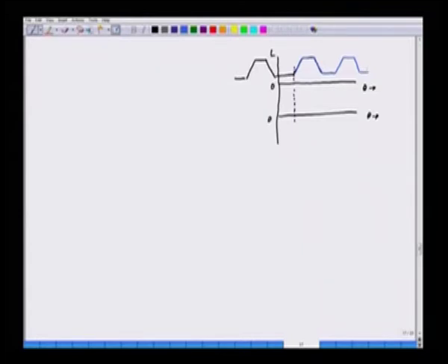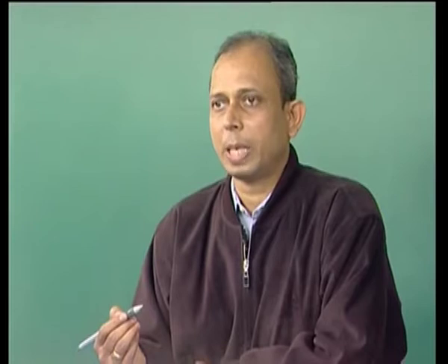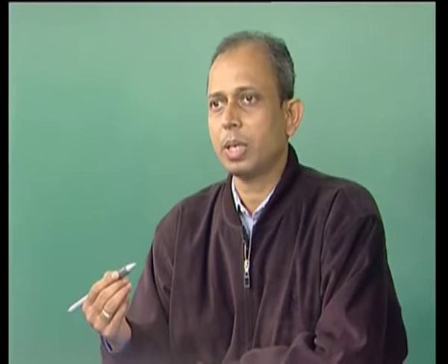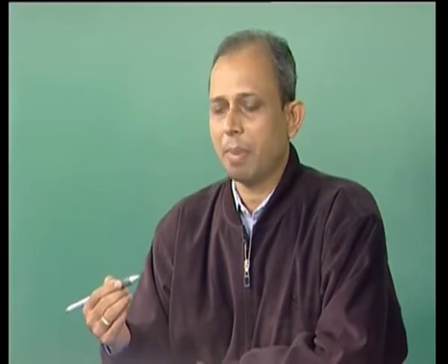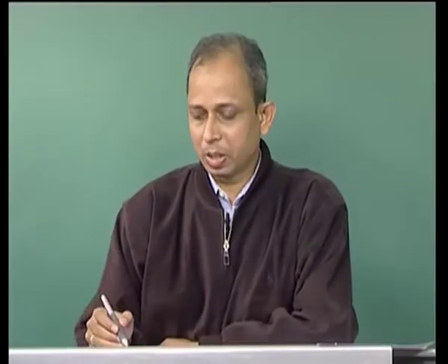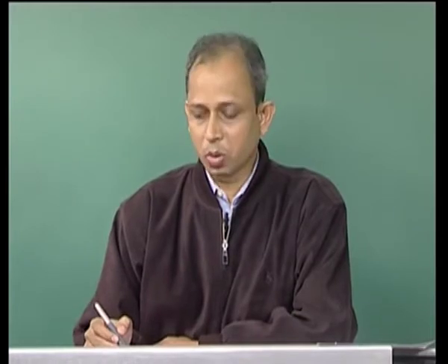When the speed is very low, the current builds up quickly. So we have to operate that in the chop mode. So the chop mode means current has to be controlled in such a way it remains within a band. So this is how the current is controlled. And then before the falling of the inductance, the current is brought down to 0. So it is only confined during the positive dL by d theta. Now when the speed becomes large beyond the base speed, this mode is not preferable. But still we have to maintain the power.